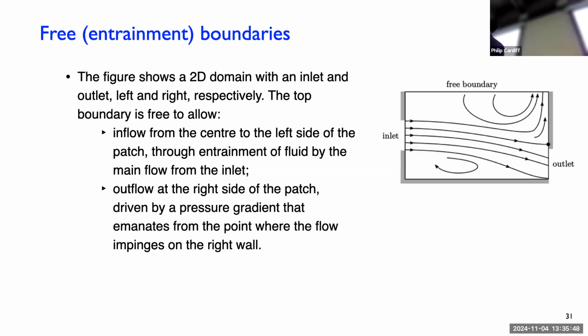And there are different ways to set those up depending on your particular application, and it can affect the prediction. A general rule of thumb is, if you have a boundary like this and you're not sure what to do, just make your domain bigger and move that away. Then it doesn't really matter what condition you set, because it shouldn't affect what's happening, like your car or something like that. But there are choices of boundaries that are maybe more physically appropriate.